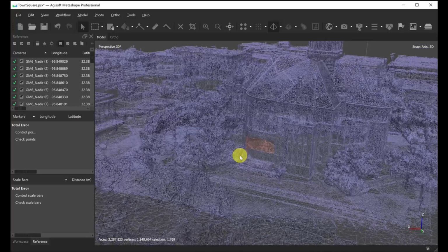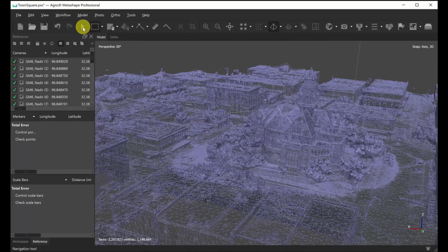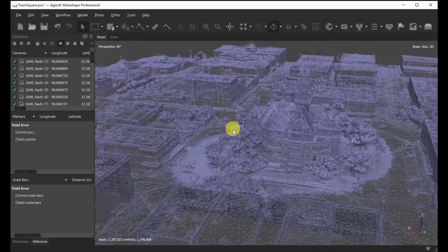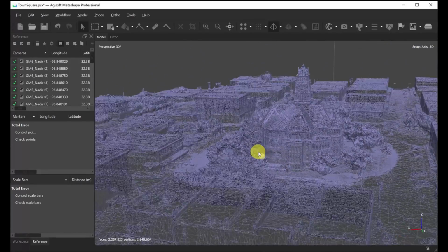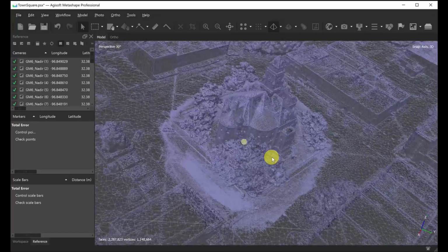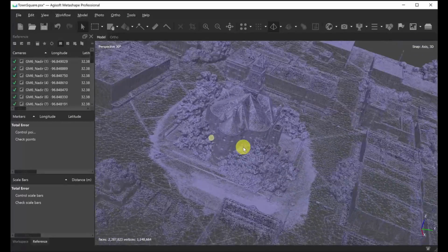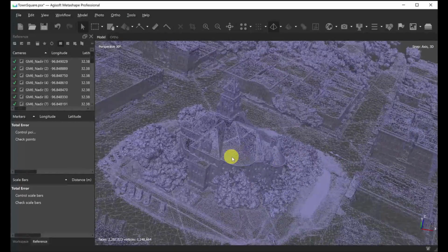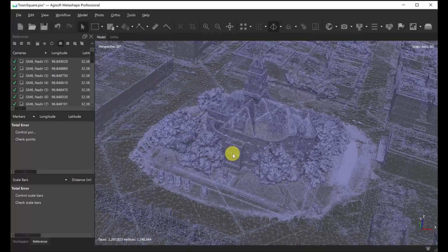So to get that to be unhighlighted, unselected, just use my selection tool and drag anywhere off of the mesh area, and then it unselects. Or you can unselect it by highlighting it with the Shift key. Alright, so that's one way just to clean up problem areas. Keep that in mind. It's been a huge saver for lots of problems for me in the past.